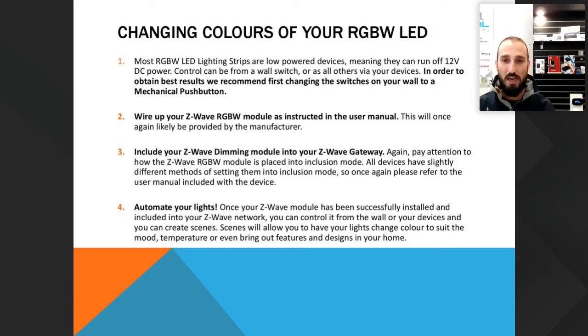So the main takeaway for all of these setups is to please make sure that, number one, you are qualified to do so and you are safely registered to install these lighting modules inside people's homes. Two, if you need to use the toggle switch, so the traditional rocker on-off style switch, please make sure that it's only during single and double switching and not using dimmers or RGBWs.